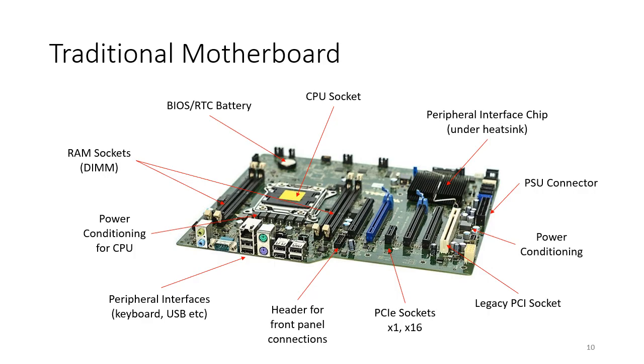So a variety of different cooling mechanisms depending on what sort of system you want. Immediately next to the CPU underneath, you can see power conditioning. So there's a set of transistors which are used to give the CPU its different voltages. We've seen a big variation in voltages over the years, coming down from higher level TTL voltages of 5 volts, then coming down to more like CMOS type voltages of 3.3 volts. And the modern CPU can run at very low voltages.